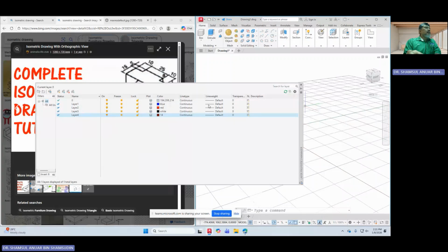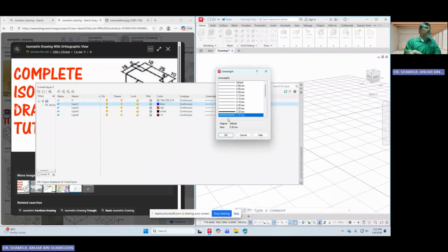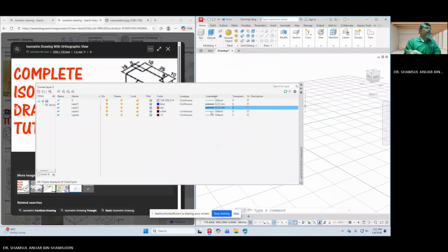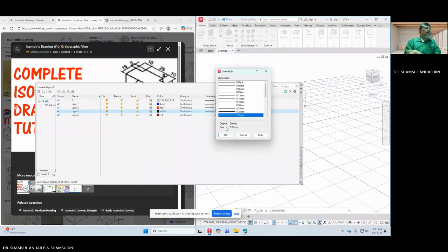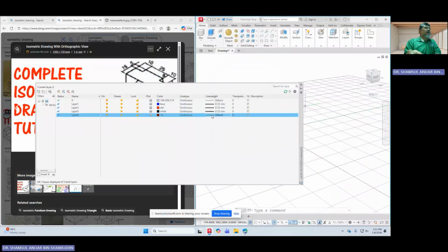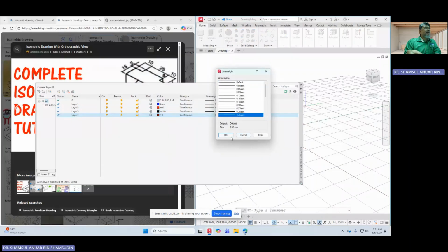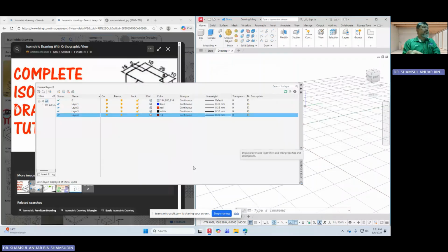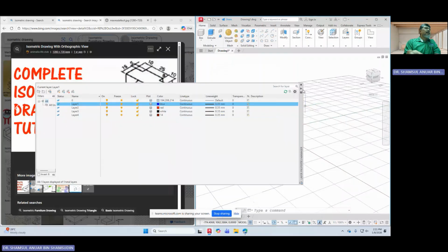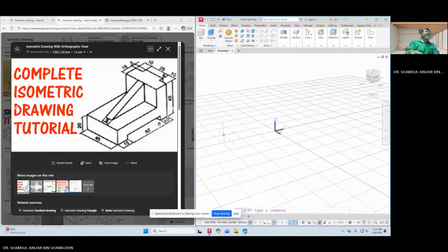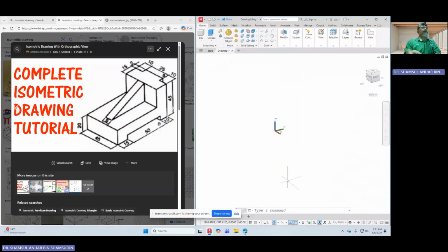All right, maybe you can also change the thickness or line weight. Sometimes 0.5 is better than just 0.35. Let's make the blue one active, so I'm going to double click there and close this. I don't want to work with the grid, so I can turn that off.